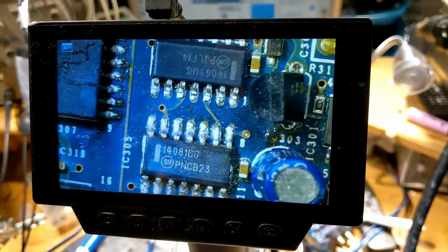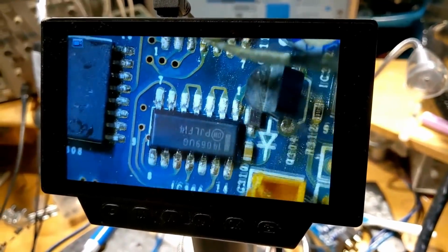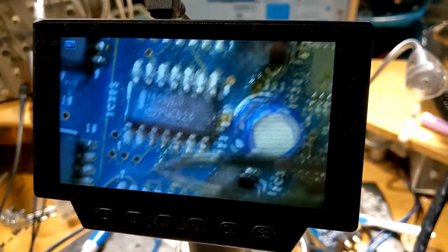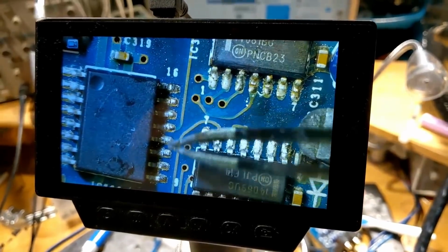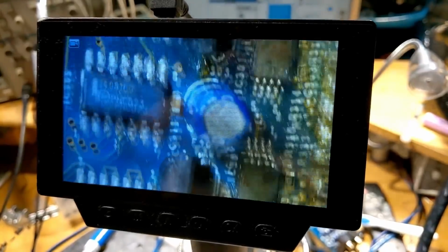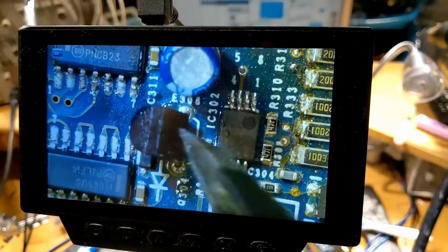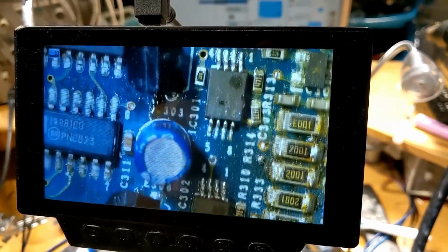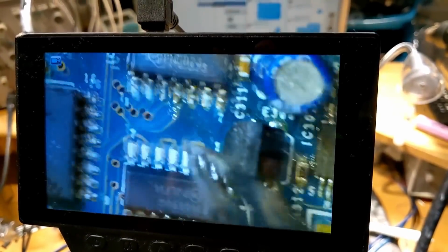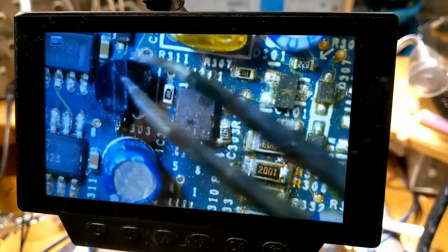Now these are kind of, how to explain, they apply the PWM drive wave to low side rail, and they split it so that the PWM rides along low side rail ready for the input of low side for the drive ICs. Now yeah, one of these had failed really badly, so I just replaced all 3 of those. Then I found that one of these transistors, which is a 5401, 2N5401, had shorted, and so I wasn't actually getting any drive to the inputs of the drive ICs because I had one of these that was shorted, so I then replaced that.